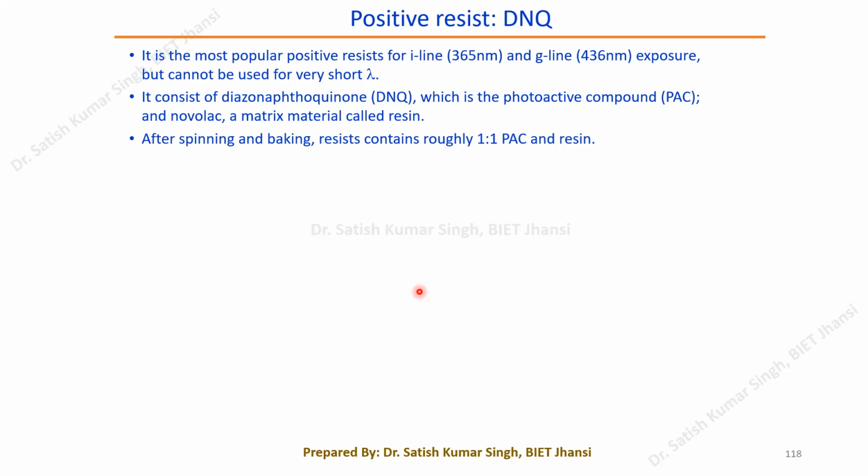We already know many things about the interaction of photons with materials. Generally, in a semiconductor material, when light is exposed, the electrons absorb the photon and go to a higher energy state. Then they travel through the conduction band, and later may recombine with the holes in the valence band and give off some energy. Or sometimes phonon-phonon interaction may take place, and the energy may be released in the form of heat, heating the material.